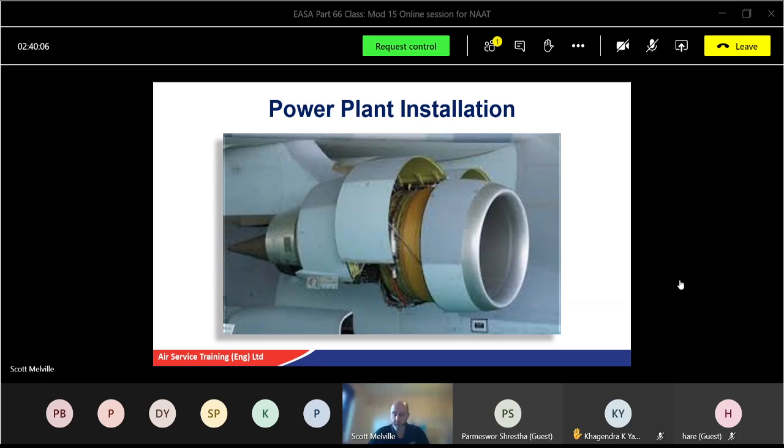Okay, LP1, LP2. Remember, LP1 at 4 psi, LP2 at 55, and then we'll shut down at 45. So low pressure switch 1 is number 1, low pressure switch 2 is number 2. Remember those. The pressure relief valve opens at what psi? 90 psi, good. Winner, winner, chicken dinner. Fantastic. Yeah, that one's all right.